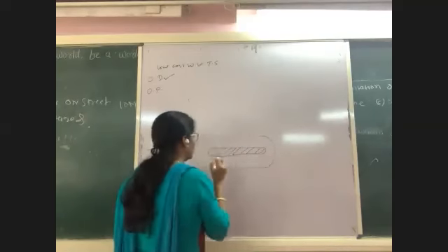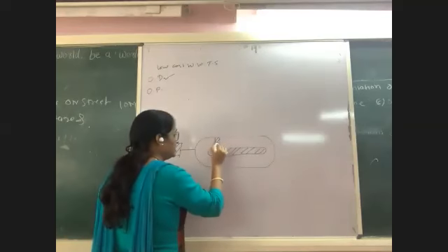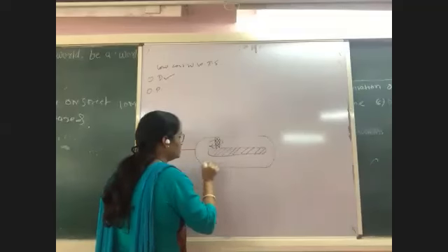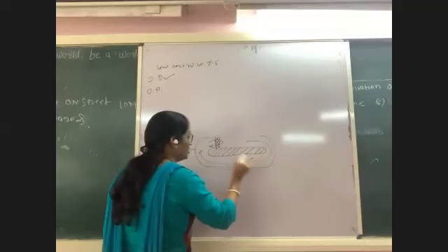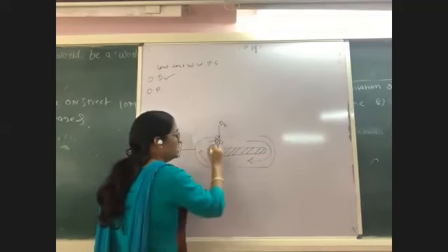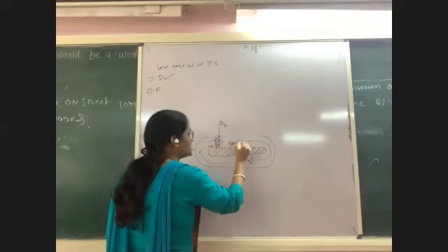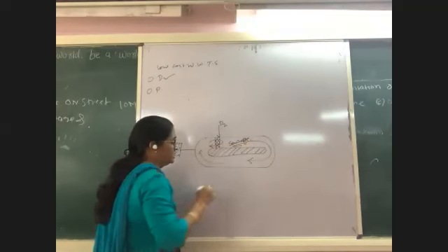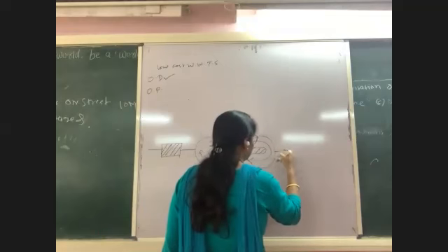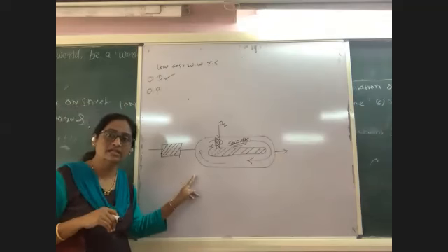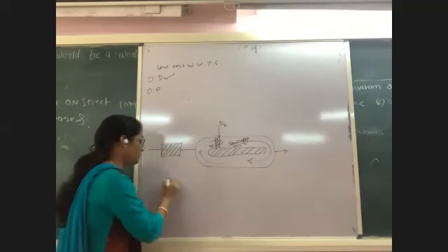Okay, so here you can apply the aerator, and that aerator will rotate in one direction. If it is rotating in this direction, the entire sewage will rotate in the same direction. This is not only providing the oxygen, but it is also making the sewage remain in suspension. So two ways it is helping us. Then the sewage will be treated, and the effluent will be the output. There are two types of oxidation ditch that can be designed. One is the intermittent